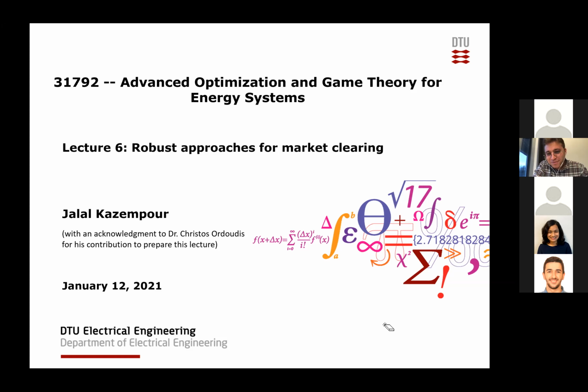Note that, for example, this part is simply our operational cost in real time under scenario 1. Our cost is the production deviation of generator 2 and load shedding. So we have a similar cost for all 4 scenarios, and for all of them, the upper bound is beta. And remember, beta is a variable.